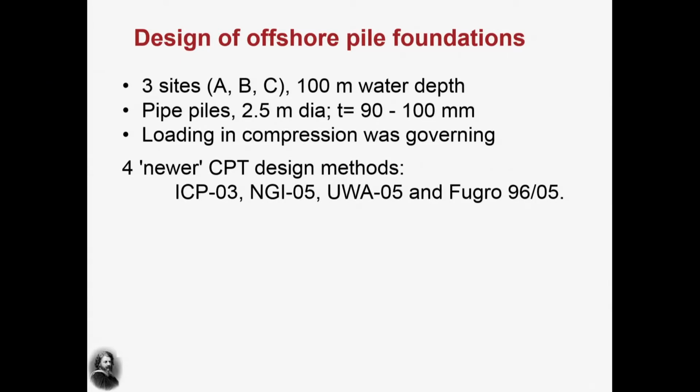So I'm going to show you very briefly the design that was done at 3 sites. They are designs which hold, and the platforms are being built. One of them is being installed this summer. 100-meter water depth, pipe piles 2.5 meters in diameter, so they're big. And in these 3 cases, the loading in compression was governing, so we look only at that.